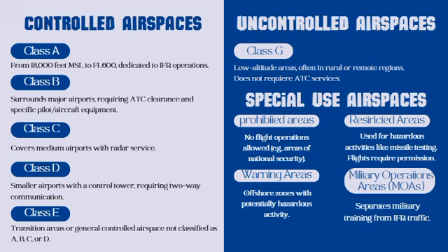Now let's continue with uncontrolled airspace. In this, we only have one, which is Class G. It covers low altitude areas, often in rural or remote regions, and does not require ATC services. Pilots are responsible for their own separation from other aircraft.